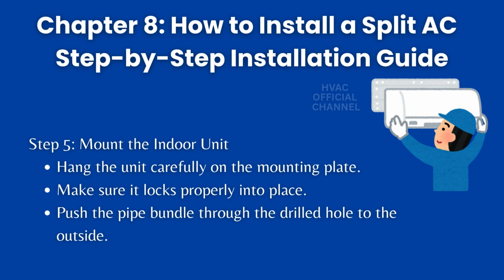Step 5. Mount the indoor unit. Hang the unit carefully on the mounting plate. Make sure it locks properly into place. Push the pipe bundle through the drilled hole to the outside.